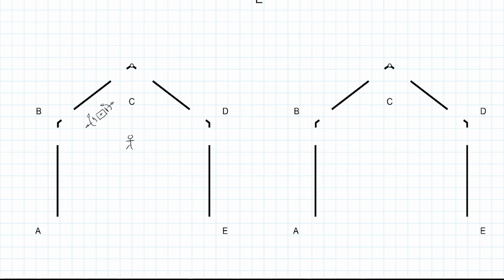So I'm going to grab my pen, grab my ruler, work my way around the shear force diagram. To start off at A, we have our reaction 21.09, pushing us up into positive territory up to 21.09. And we know that we arrive at the far end at a value of 3.91 going up, or away to the left. It gets a little bit confusing in global coordinates, 3.91 going to the left. And so that's going to be a negative shear for us.